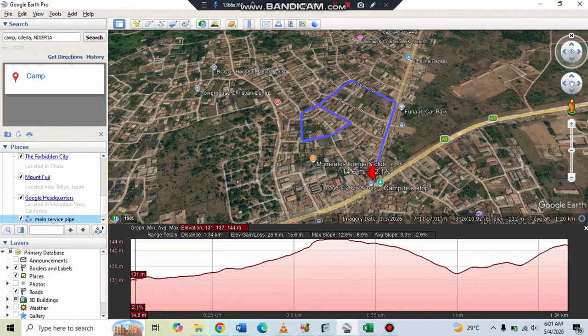So in this case we can decide to locate our source of water anywhere around here, but the important thing is that we may likely place our overhead tank somewhere around here, which is where we have the highest elevation. This is economical for a designer and the consumers in the sense that once water is pumped to the highest location there, it now flows by gravity to any of these areas where the pipes will be located, and this saves costs.